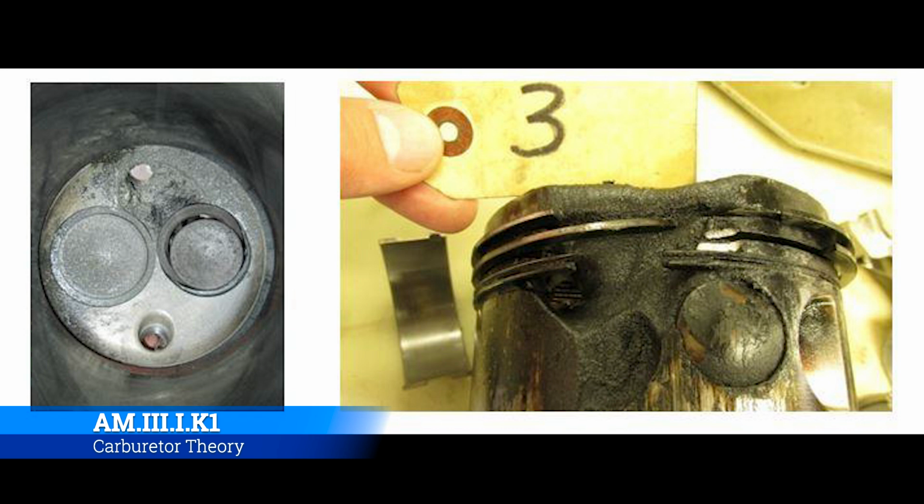With the fuel in there, it's going to want to stick to the sidewalls of the chamber. But then whenever the next cycle happens, it's going to get another puff of fuel into it, and now you have too much fuel in there. And then as that piston comes up, one of the things that can potentially happen is called detonation. That's where instead of having a nice clean burn, effectively you just have a bomb and it blows up.